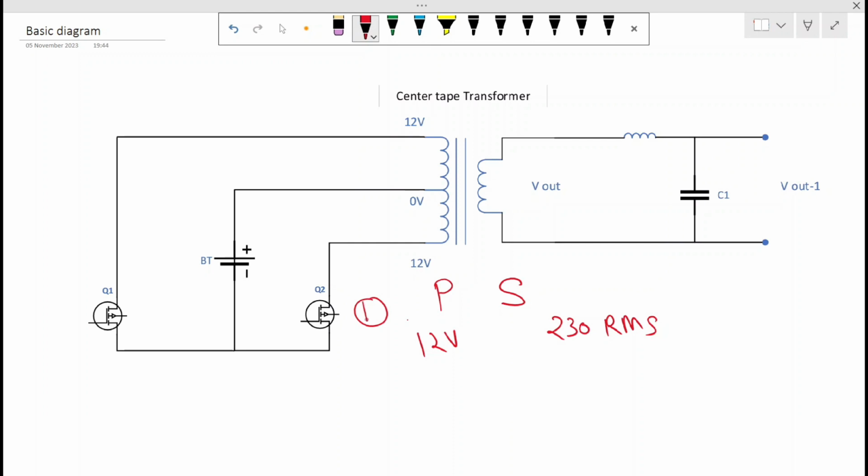Like this, we connect the MOSFETs in parallel with each other, and the same here also, to increase the power rating of the system. The gate drive will connect individually with one resistor to the gate circuitry, and the same here also. In this manner we can increase the power rating of the system.